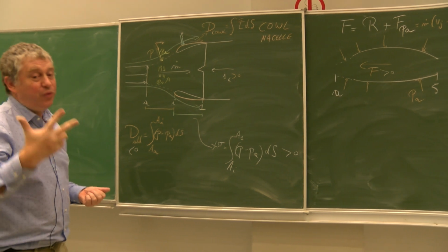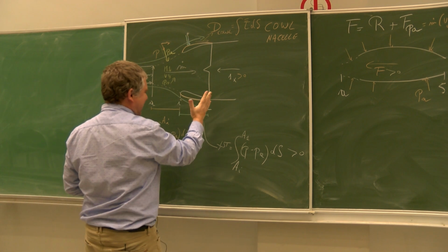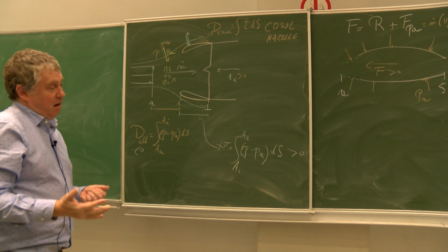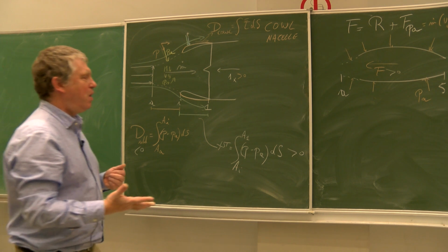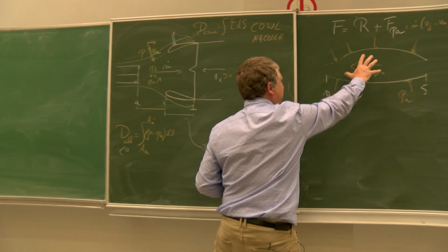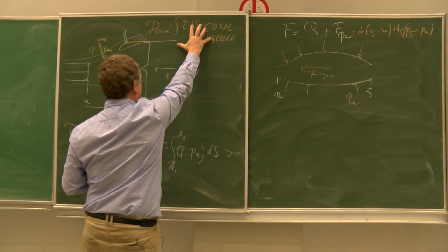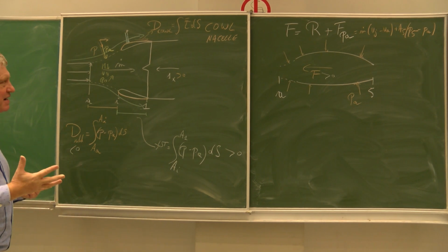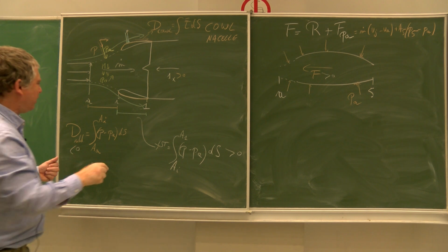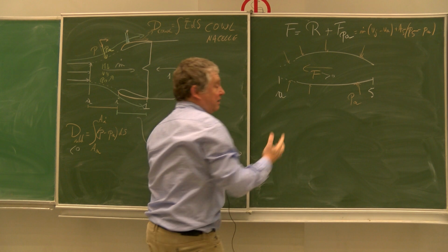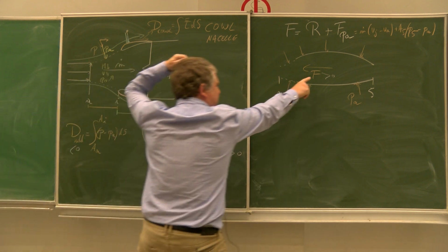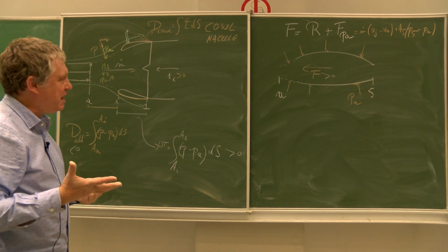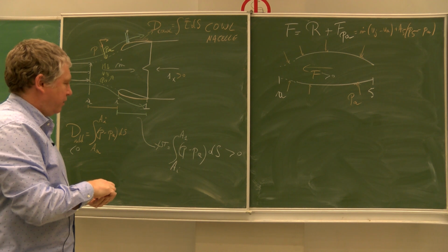So in fact, there are 3 forces for the intake. 1, 2, 3 that we have not considered before. Of course, the choice will be up to you. Do you want to add this one to the aircraft drag? Do you want to add this to the aircraft drag? This is a decision that you need to take. Or do you want to make the sum of this and to add that and to add this sum to this term? This is up to you. This is what we will call the thrust drag bookkeeping that we will discuss later on.